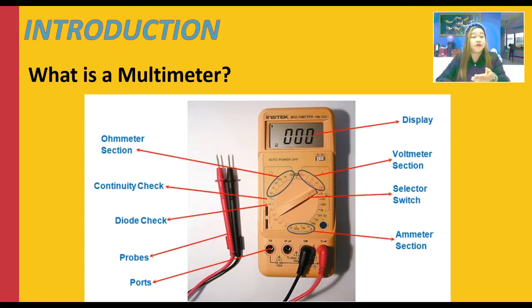The face of a digital multimeter typically includes four components: the display to view the measurement readouts, the buttons to select various functions, and I think the options vary according to model, and then a dial or a rotary switch to select primary measurement values such as volts, amps, and ohms.